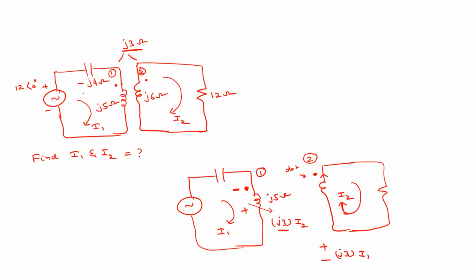So now, this one is a voltage source, right? This is a voltage, right? Agree? Yes, sir. But here the current is I1, while this voltage magnitude is controlled by the other circuit current I2, right? So how will you represent that? This can be represented by a dependent source. Agree? So how will you represent this dependent voltage? It will be something like this.